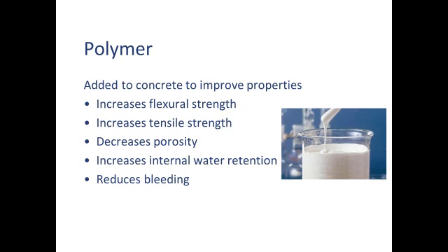And although the polymer doesn't make the mixed water thicker, it can help reduce bleeding because it can help make the concrete more consistent. It tends to be a workability aid. It's not a super plasticizer, but it can help your mix move around a lot better, so you don't need to add extra water.